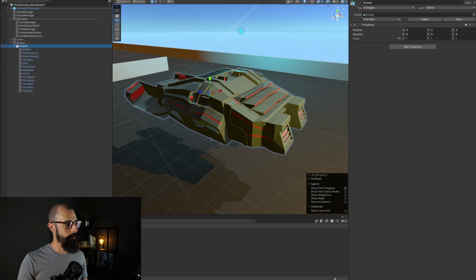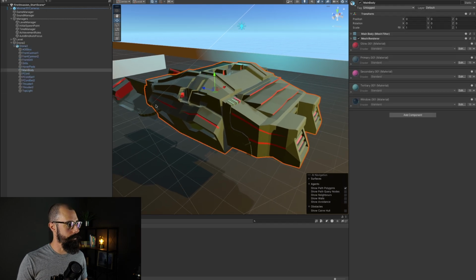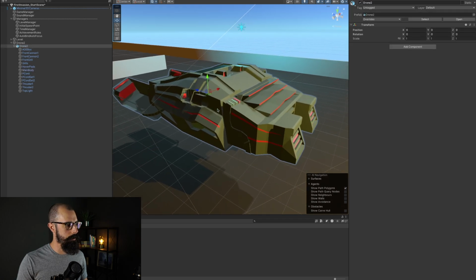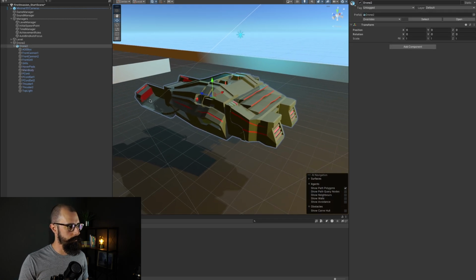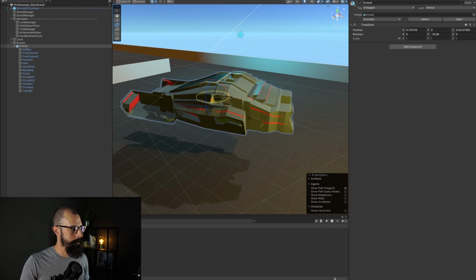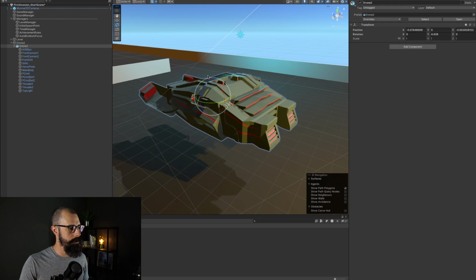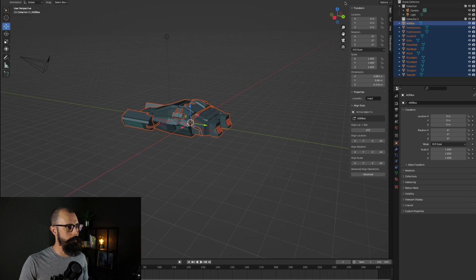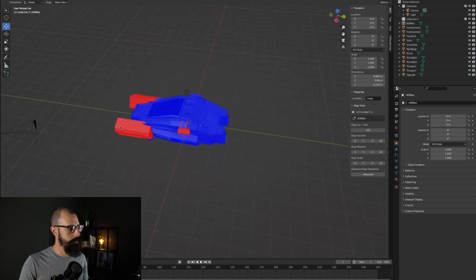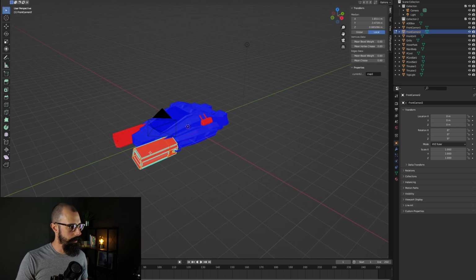Wonderful. So we actually have the model here. We have it imported. Looks like some of these things might be negative. So what's interesting here, and again, this is not a Blender tutorial, but if I spin this around, you're going to notice that some of these spots are empty, which is not good. That's something I need to change. What we can do, if I remember correctly, is look at the face orientation. So I went up here to the viewport overlays, face orientation, and I actually need to jump into these. And I think I can flip the faces.